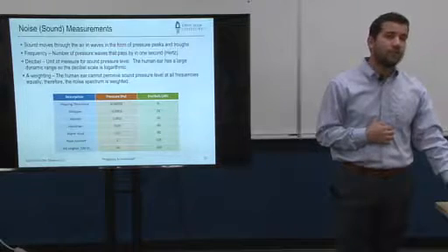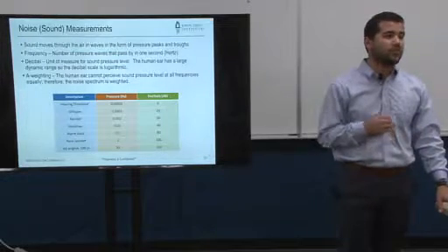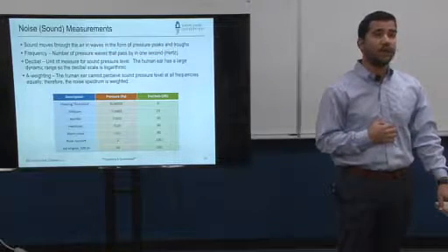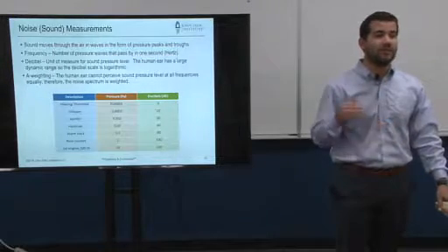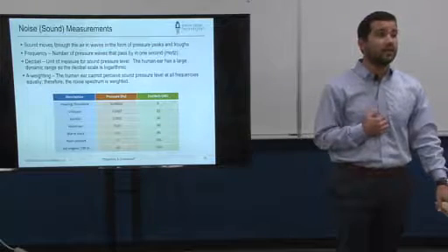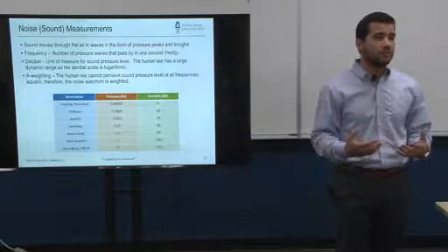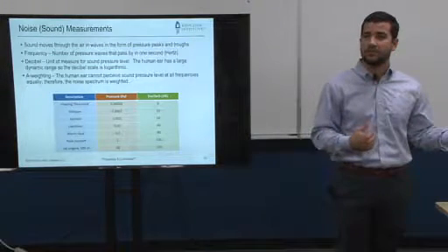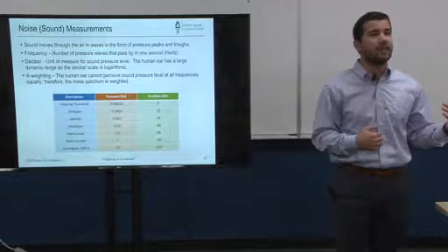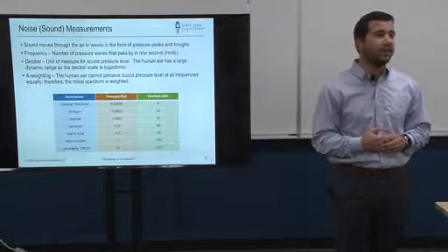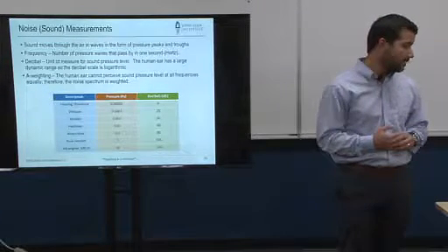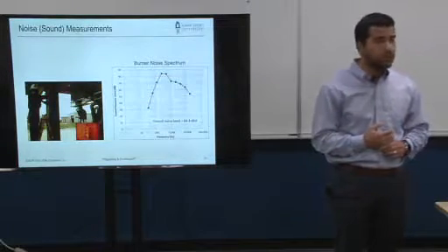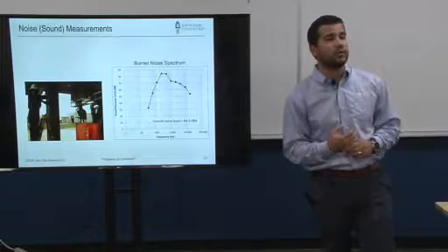Another pollution that we actually record, and that is regulated, is noise. Burners are loud, and we typically have a threshold that we need to meet. As human beings, we really cannot hear all the different frequencies, so there is an A-weighted scale that we work with called dBA, and we pretty much record it on every single one of our burner tests.